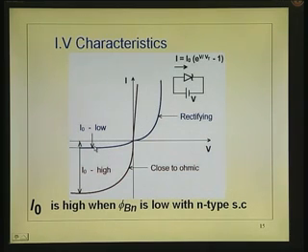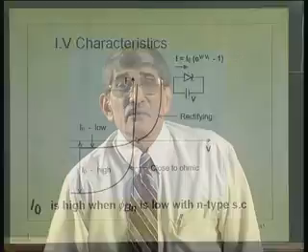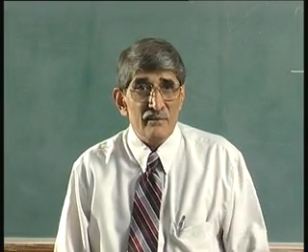If I naught is large, how will the characteristics be? That is this one. I naught is large means the whole thing comes down here. What happens to the forward characteristics? I naught is very large, so with small values of V, I get the same current. So, the entire characteristic moves like that. Now, it tells you the entire information that you are looking for.